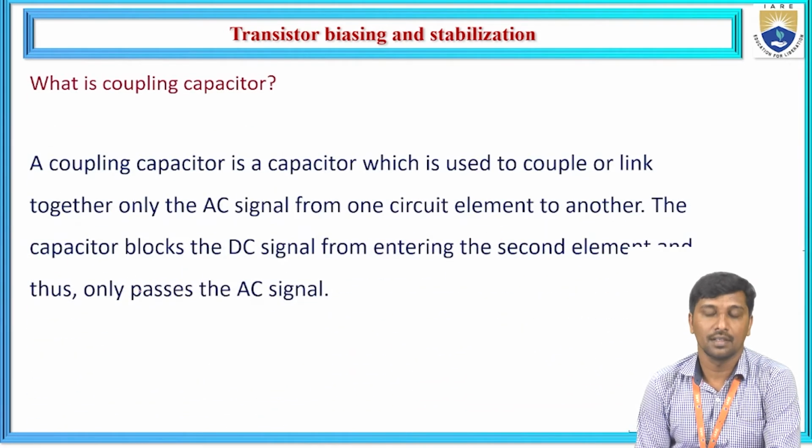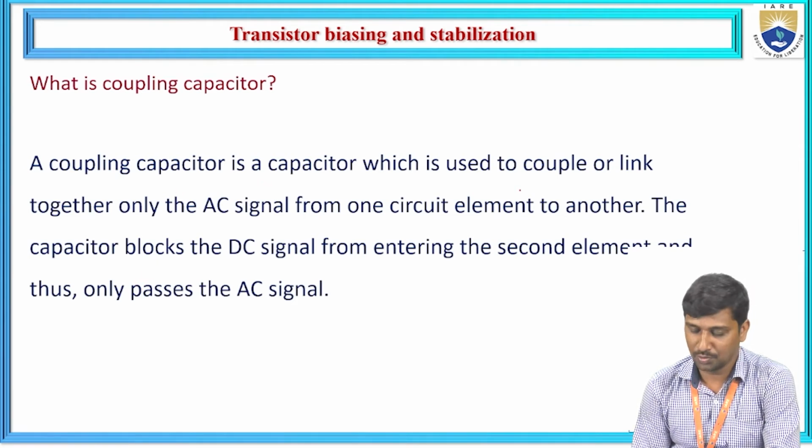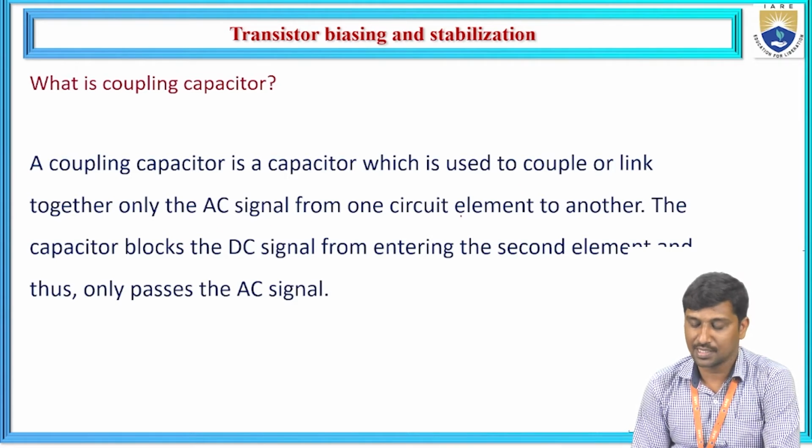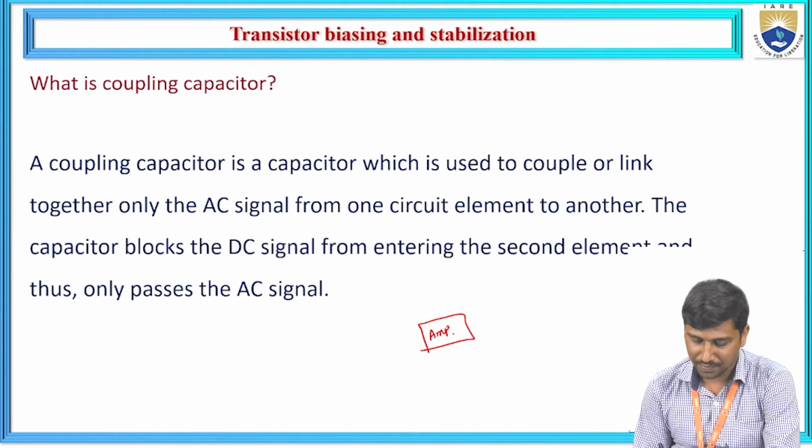Now, similar to that, what is a coupling capacitor? A coupling capacitor is used to couple or link the AC signal from one circuit element to another. If you understand this as a stage amplifier, for this amplifier we pass the input signal through the capacitance.